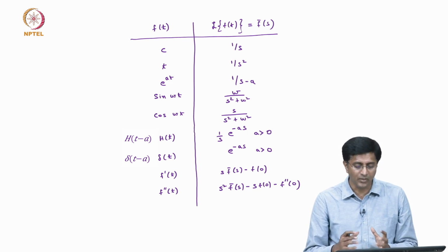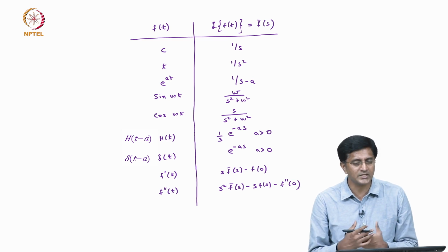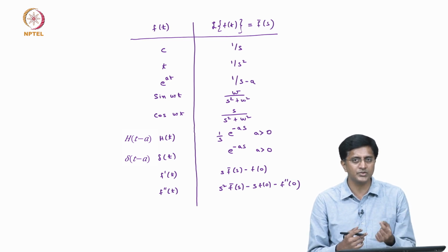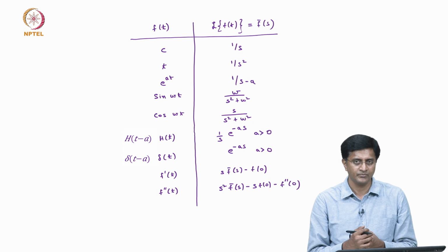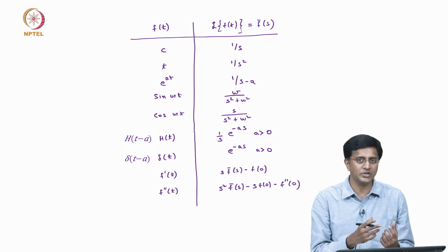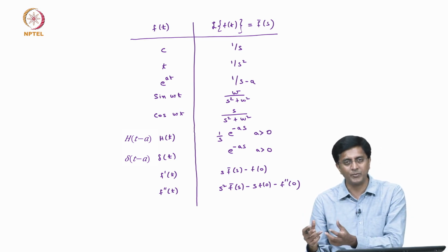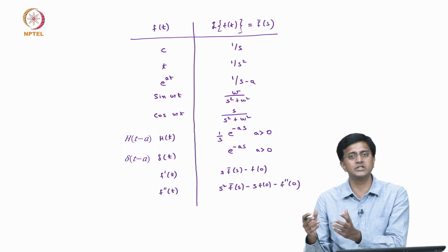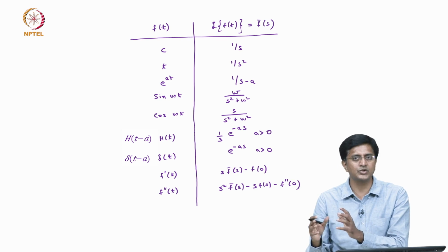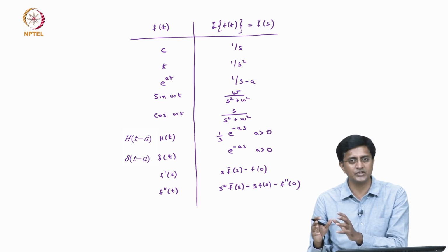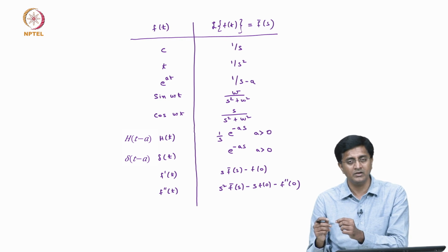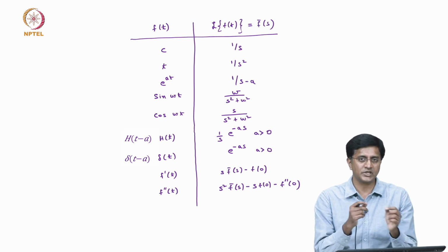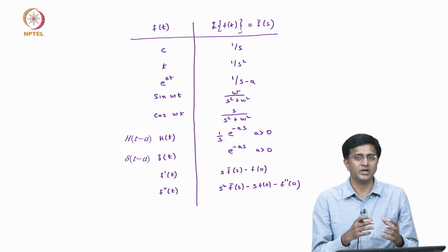So, this is helpful because we said the viscoelastic behavior can be represented using differential equations. So, when we take these differential equations and look at them in the Laplace domain, these differential equations will transform into algebraic equations. So, once you do the algebra and simplify those equations, then we again do the inverse transform and come back to the time domain.